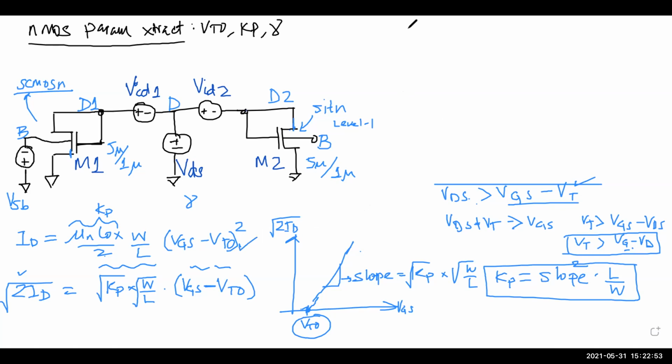So that's why, in the analog world at least, this is called a diode connected transistor. The reason it's called that is from BJT, because in BJT, if you connected base to the collector, this is nothing but just a PN diode, right? So a lot of times you'll see it referred to as a diode connected device.